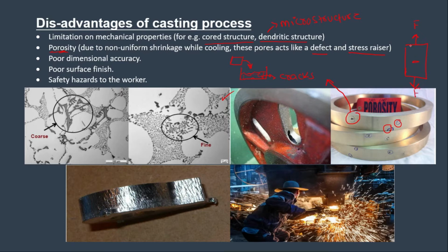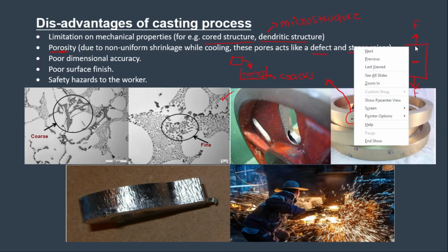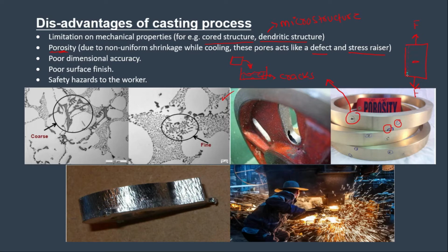This force is being borne by the material. These are the force lines. But as soon as the force lines come here, they move this way. So you can see the force lines are being concentrated at these edges of this pore.